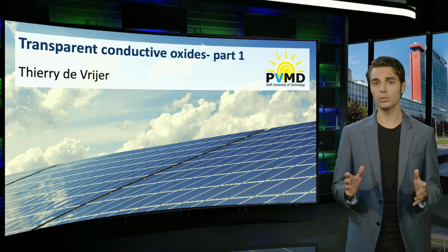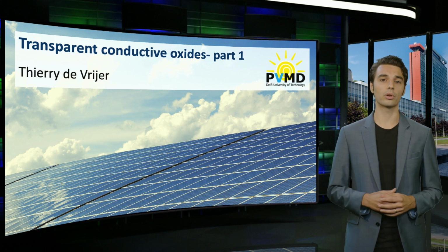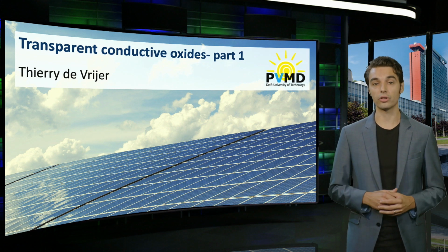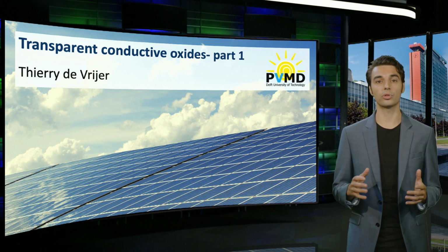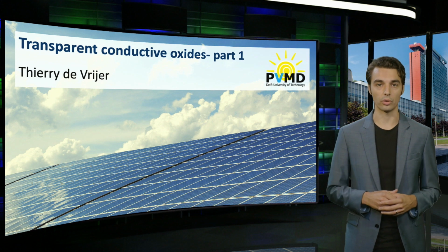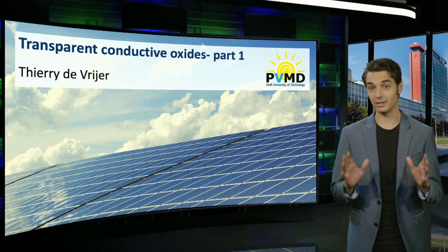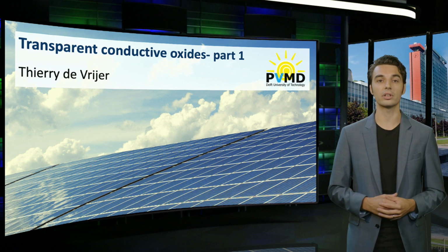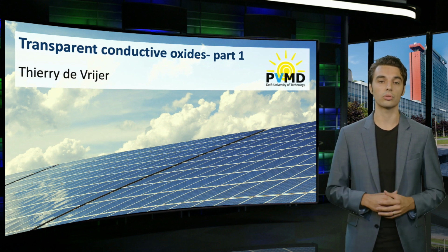But before we do, we will discuss some concepts that are important for more than one of these technologies, such as the PIN junction, light management in thin film solar cells and multi-junction solar cells. Additionally, in this video, we'll discuss a class of materials known as transparent conductive oxides, or TCOs.